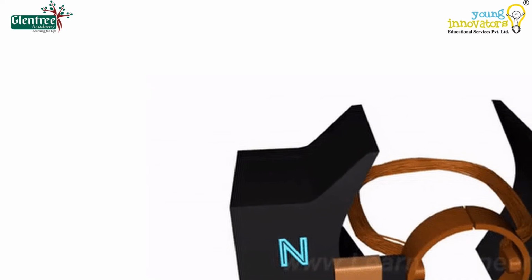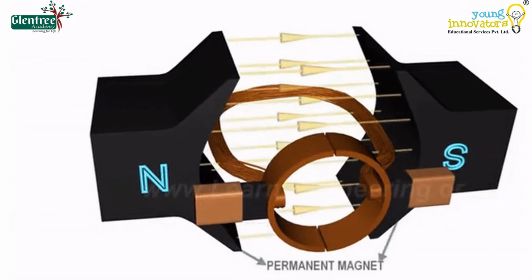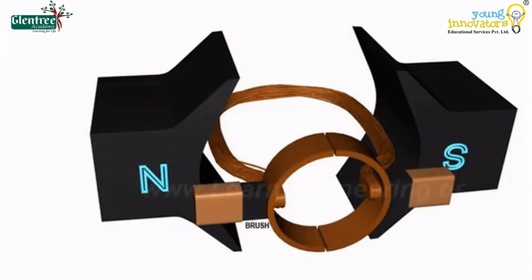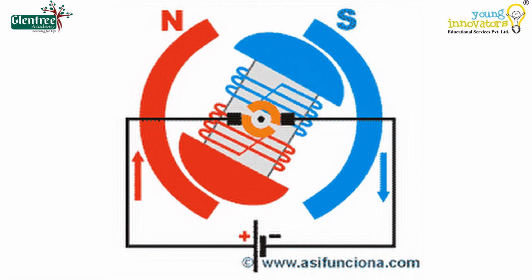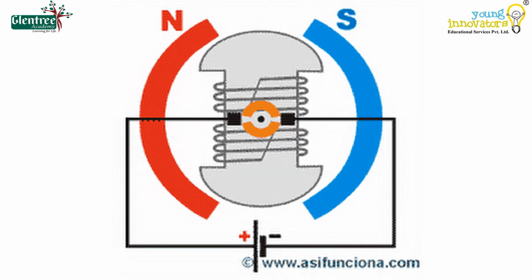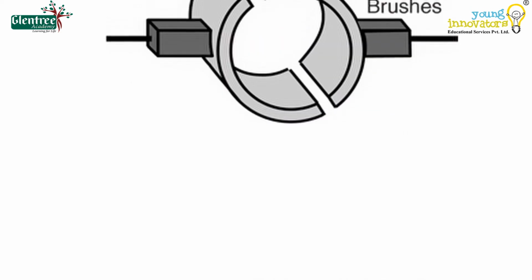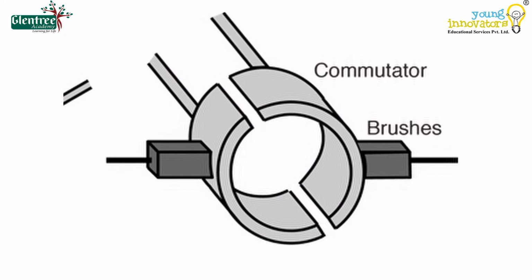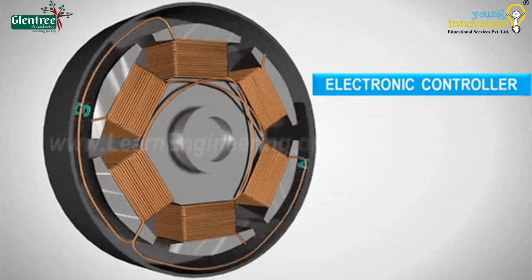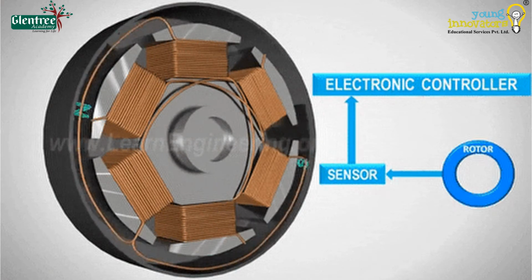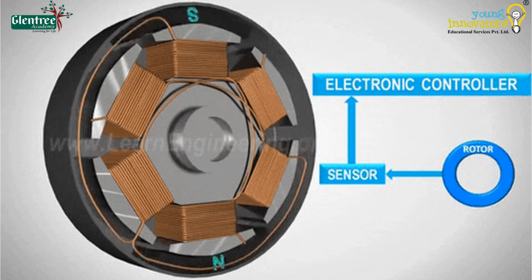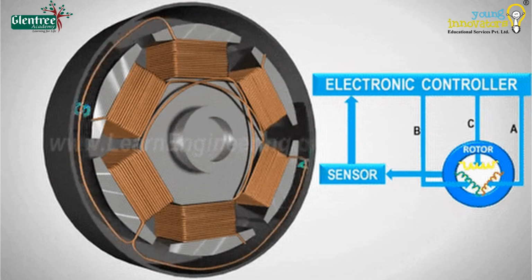Commutator is another DC motor part which is connected to the armature, enabling this switching of current. The commutator is designed to commute the supply current to the armature winding from the mains. The commutator passes through the brushes of the DC motor. The last part of the DC motor is the brush, which is made of carbon or graphite structures.